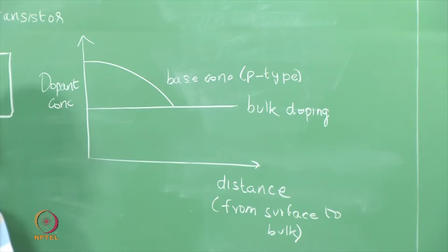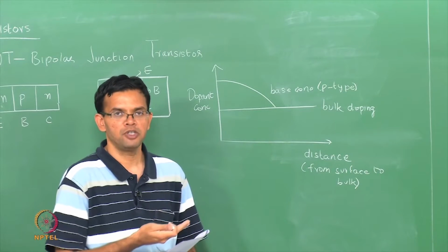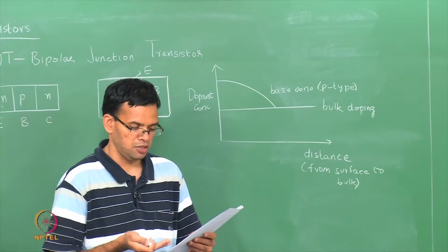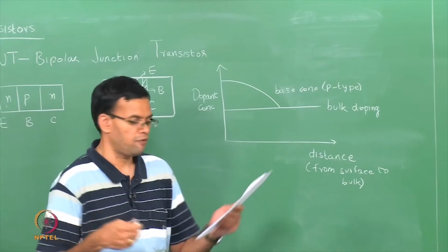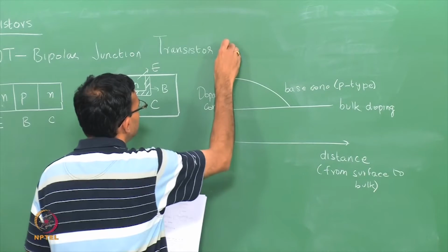We now have to define the emitter region, which is again N type. This region has to be closer to the surface. So, we typically use a vapor source with a higher concentration in order to create your error function profile. Let me just extend the axis a bit.